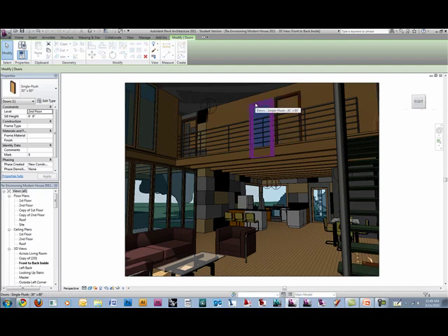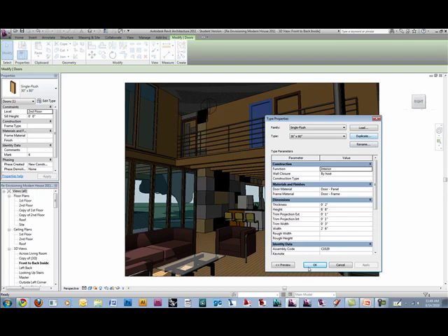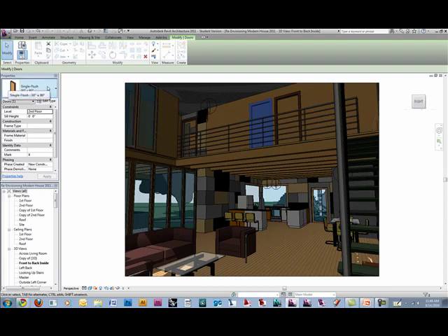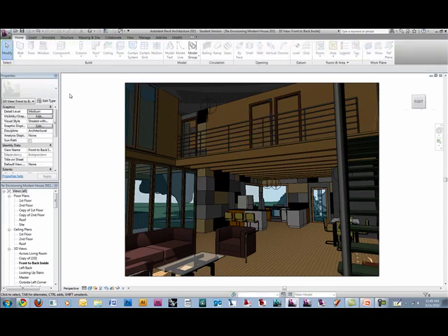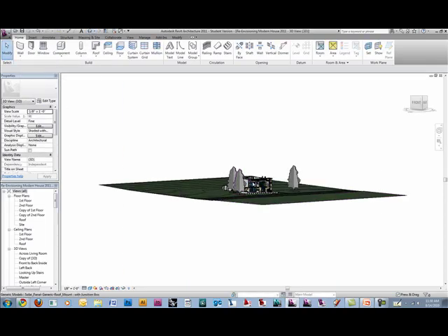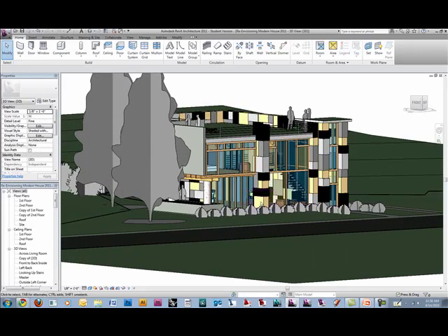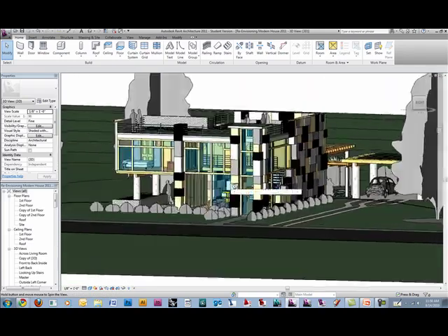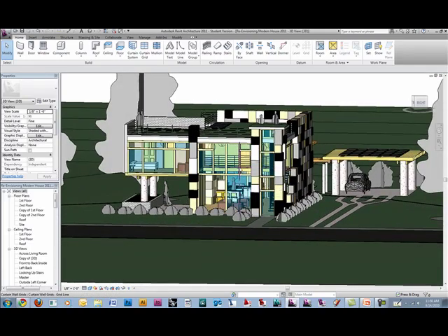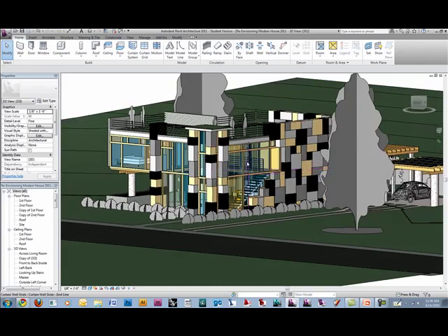Yeah. So to do that, all we want to do is go to edit type. I always forget this actually. That's true. You can't edit it well in the 3D view. Same thing that happened last time. Yeah, in a plan view or a section, then you can sort of edit families, but it won't let you in a 3D perspective view. You can't edit it in the camera. Yeah, I don't know why. Couldn't you do that in 2010? I think that's why I keep doing it, because in 2010 I think you could. It's going to be hard to get to this door.